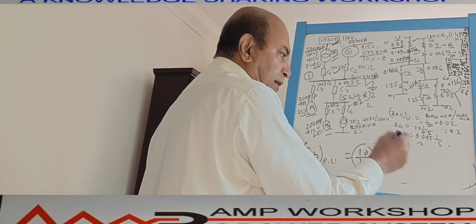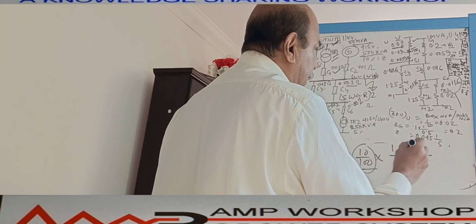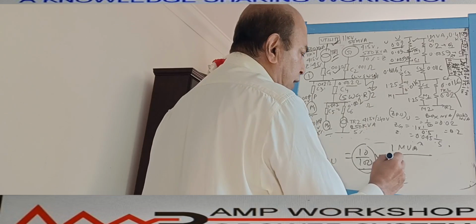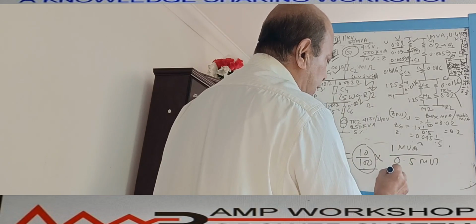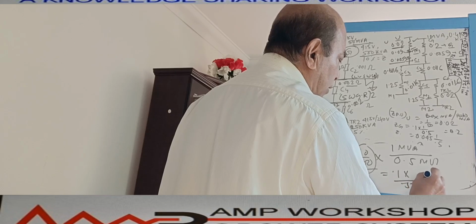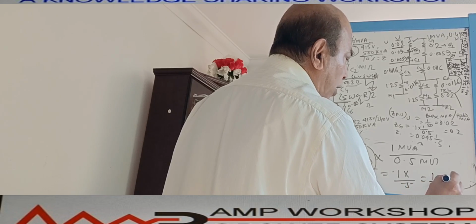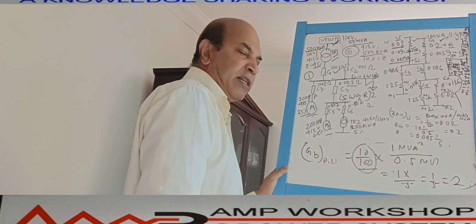So this into base MVA. Base MVA means 1 MVA, right? And base kVA and this rated MVA, rated MVA is 0.5 MVA. So that is equal to actually 0.1 into 0.5. That is equal to 1 by 5, equal to 0.2. So that is what we have put over here. Generator per unit impedance 0.2.